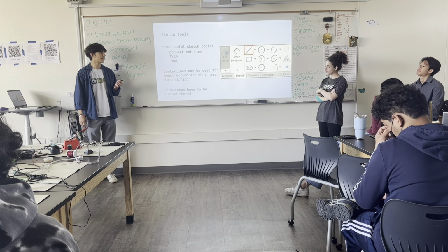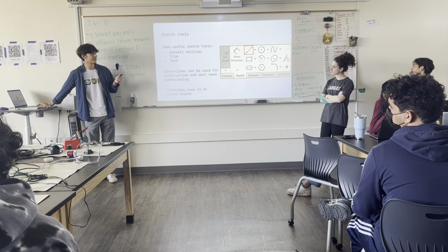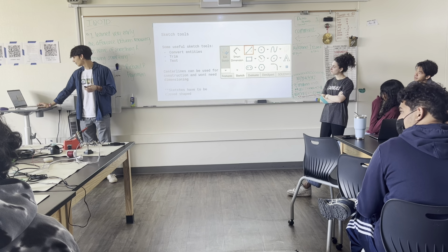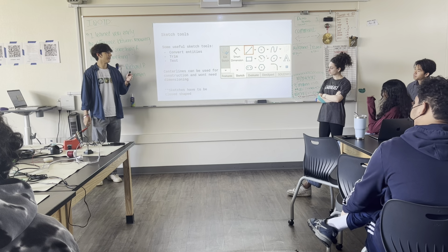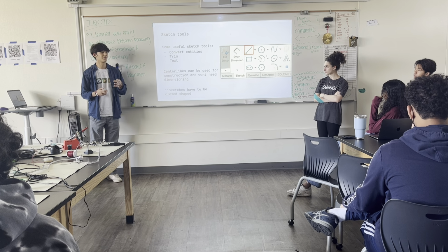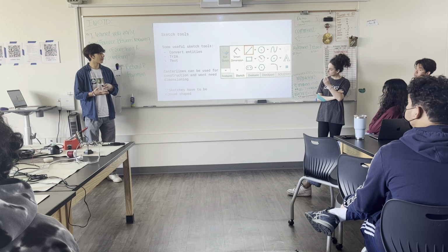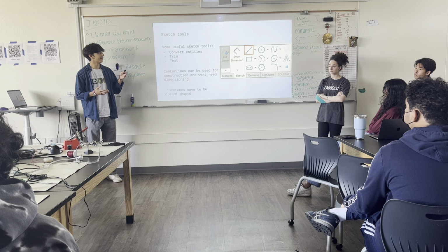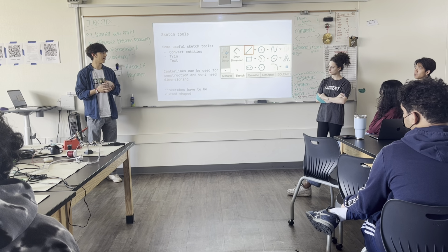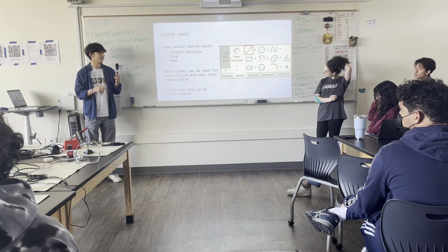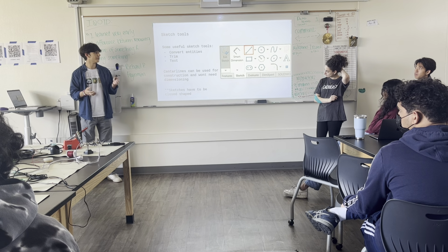And so here are some more sketch tools. This isn't Onshape, but this is SolidWorks. It's pretty much the same thing. All of your tools are the same. You have lines, rectangles, different circles, different arcs, and each has a drop-down menu which you can select a different type. So for example, the arc has a tangent arc, 3-point arc, and a center arc. The circle, I'm pretty sure you can do based on clicking in the top corner and making a circle, or the center. Rectangle you can click from the corner, and you can also do it from the center. So you can just choose the best way you want to model something due to your needs.